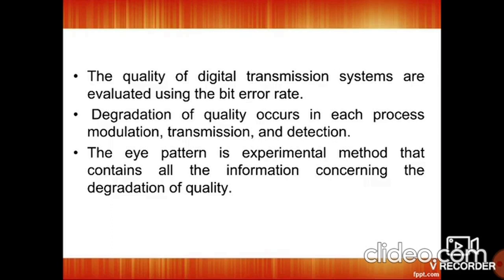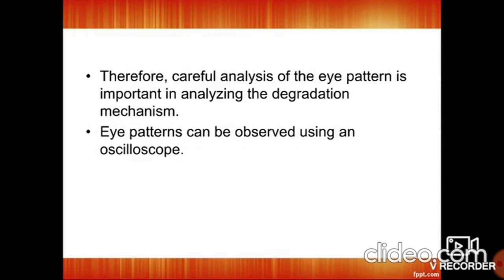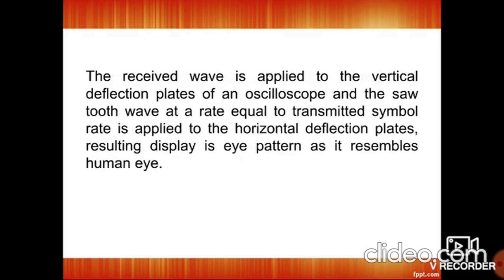The eye pattern is the experimental method that contains all information concerning the degradation quantity. Therefore, careful analysis of the eye pattern is important in analyzing the degradation mechanism. So, this pattern can be observed using an oscilloscope, which is used to identify the inter-symbol interference.